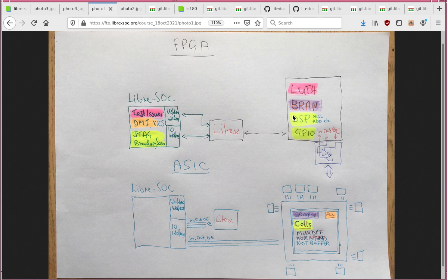So if you have 4 inputs, you have a 16 entry state table, which, based on any of the possible combinations of the 4 inputs, will produce outputs. And this basically allows you to emulate, and I do mean emulate, XOR gates, MUX gates, NOT gates, NAND gates, AND gates, and all the standard gate things. Now, one thing that LUT4s can't do is they can't be a BRAM, a block RAM.